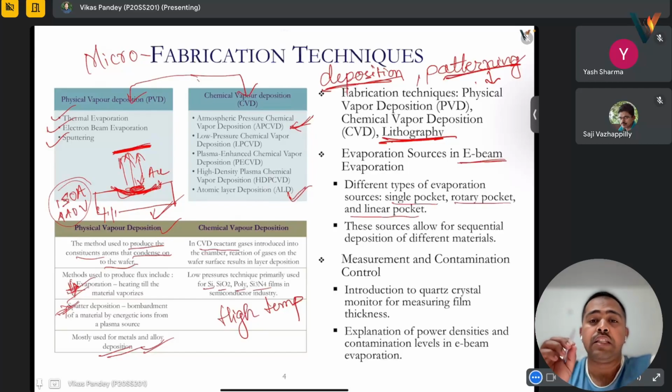Okay, these sources, like many a times you must have heard that though we see the electrodes, you might feel like there is gold over it or something, but it is not a single layer. It can have multiple layers like chromium, titanium, gold, nickel, gold, based on our uses. To have a good ohmic contact, we might need different layers.